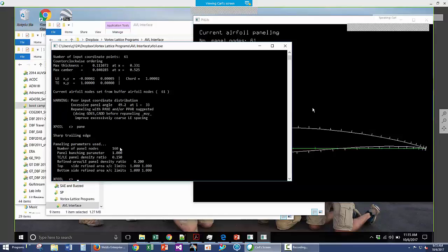You don't have to memorize any of these commands. Step by step, everything that I'm going to show here is in that Xfoil tutorial. And most of it is unnecessary anyway if you're using something like XFLR5 to automate the airfoil analysis. You'll see this is a very clunky interface in terms of having to type stuff in manually, but I can do it very quickly if I know what I'm doing. If you don't, then sometimes it's easier to use a GUI. If you know exactly what you're doing, it's not actually that bad.